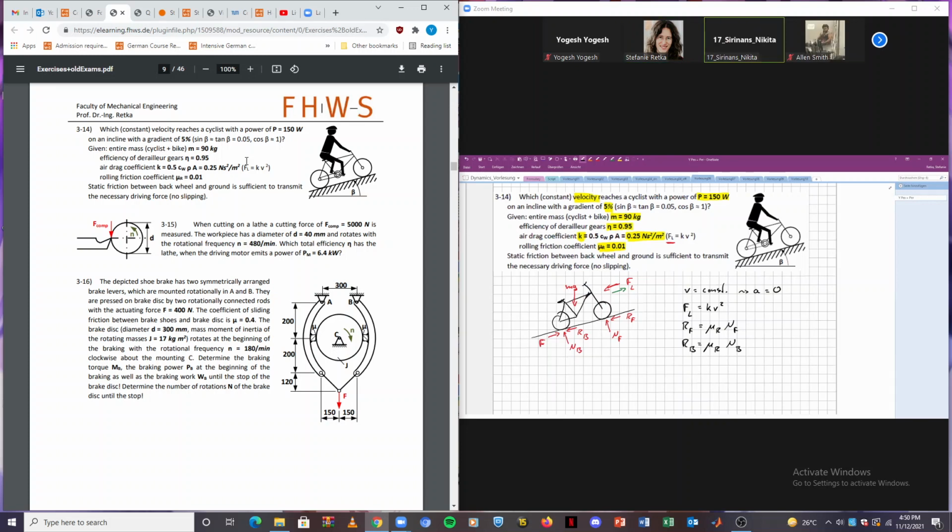Sorry, Professor. Quick question. The normal force will be equated to the mg, and it will be equally spread between two wheels, right? Yes, but the normal force on the front wheel and back wheel might not be of the same size. They are only of the same size when the center of gravity is exactly in the middle between the back and front wheel. Okay, thank you.